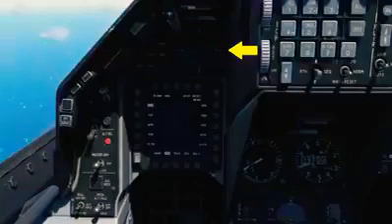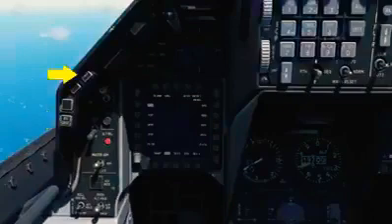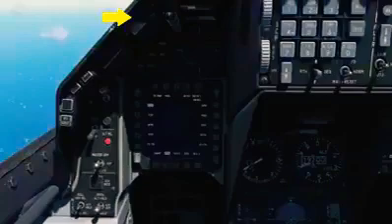Along the top left side of the instrument panel are another set of lights. These include the following. Pressing the IFF identification button initiates an IFF response to an interrogation or request from air traffic control. When a fault appears on the Pilot Fault List Display or PFLD, the Fault Acknowledge button is pressed to clear the fault. The Master Caution light will illuminate anytime a warning light is lit to indicate a malfunction or a specific condition has occurred. It does not illuminate with a caution light. It can be reset by pressing the light button.